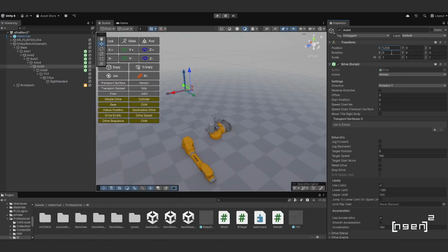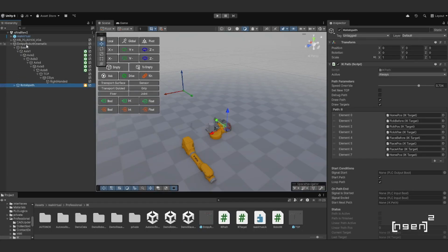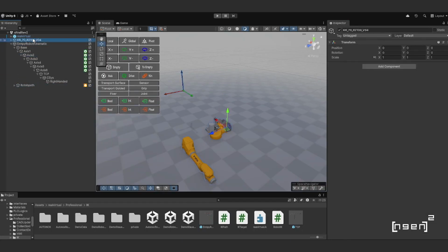And keep in mind unit conversions when you're in Unity, it's in meters by default, and most of the spec sheets will have millimeters. You want to be mindful of that. So yeah, the next step here is we're gonna get the robot to match the orientation of the empty game object. So we'll go ahead and rotate this to the right position.